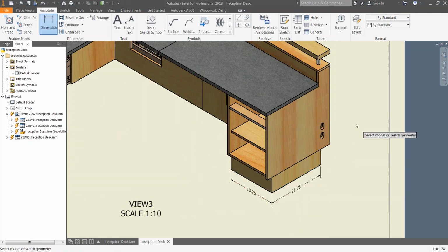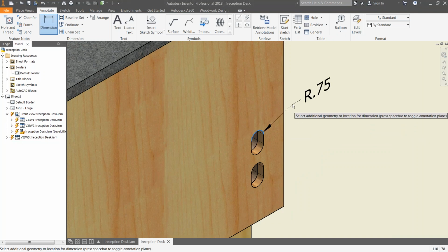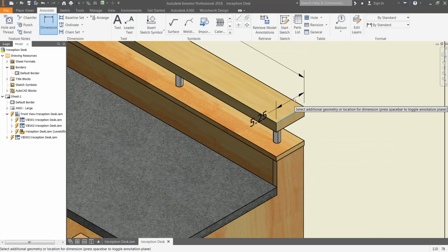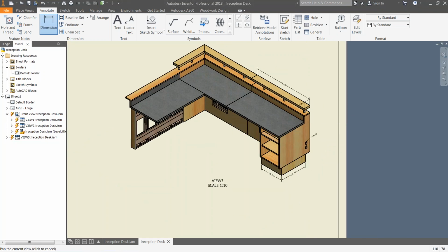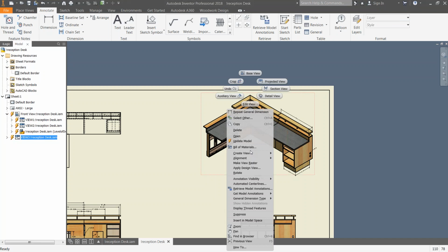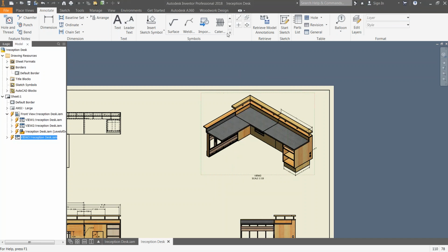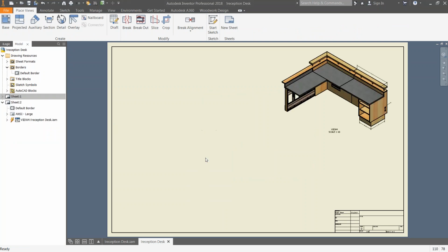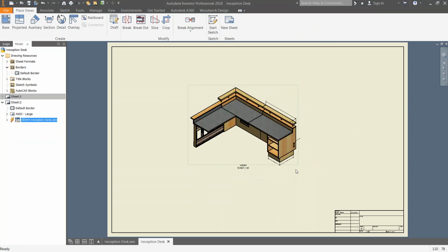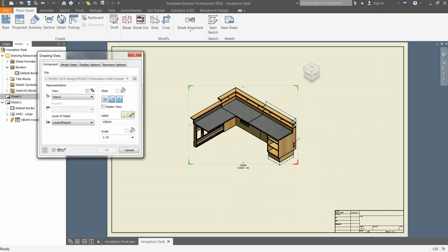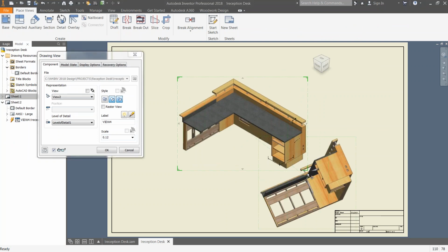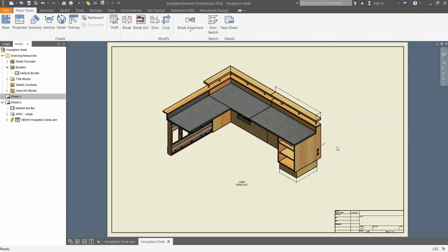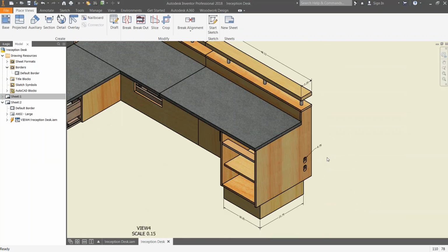So here, what I'm doing is I'm dimensioning isometrics right now. Everything here is real at all times. You can take isometrics. You can right-click on this and say copy. You can say I want to create a new sheet, and I can say paste. We've got a new sheet, and the dimensions come with it. And if we open up, if we scale it up, like I'm doing here, by just touching this arrow, all the dimensions stay accurate and at the correct size.